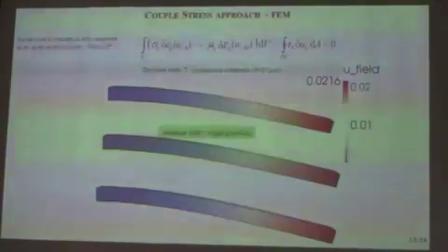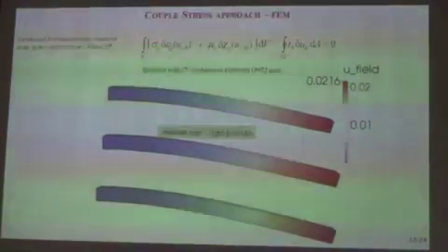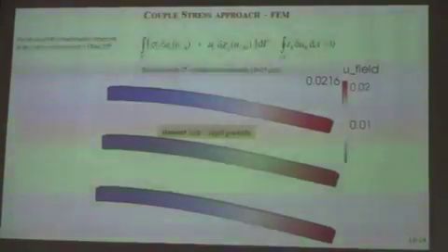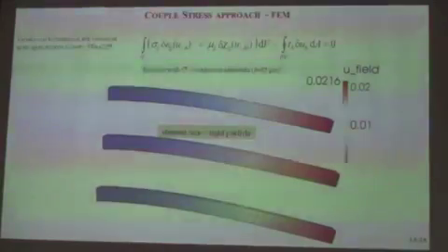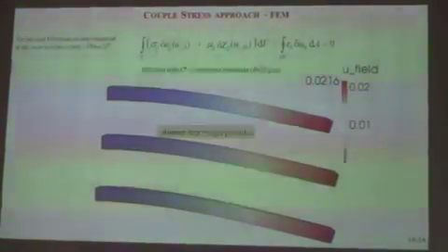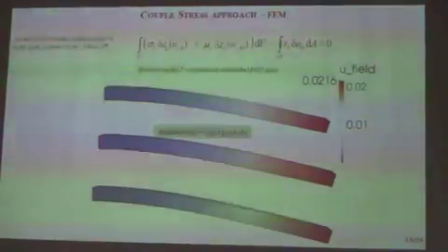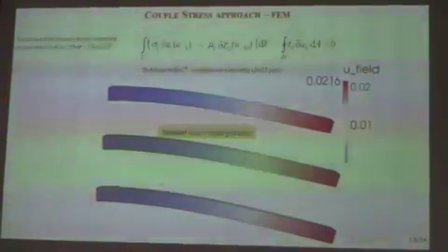And I get good beam bending displacement fields out of it, but as I checked for the convergence of it, I realized immediately a dependency on the mesh, and I checked that the element size somehow behaves like the size of the micro particle we talked about a few slides before.